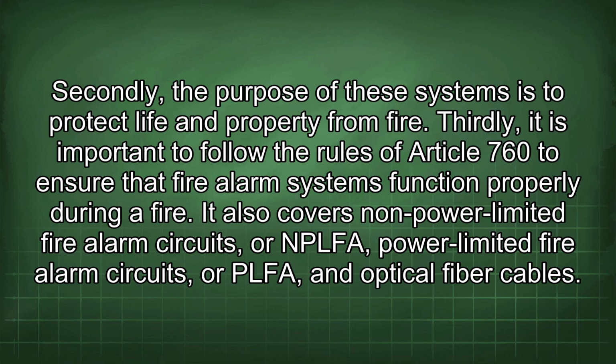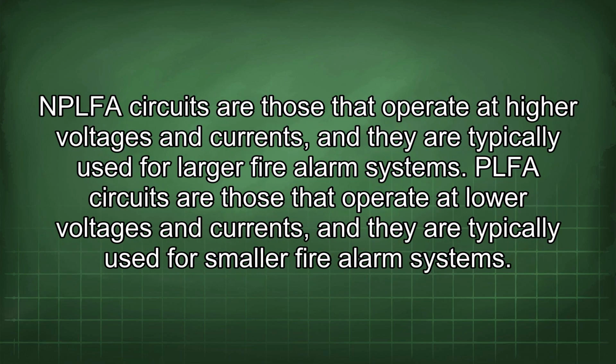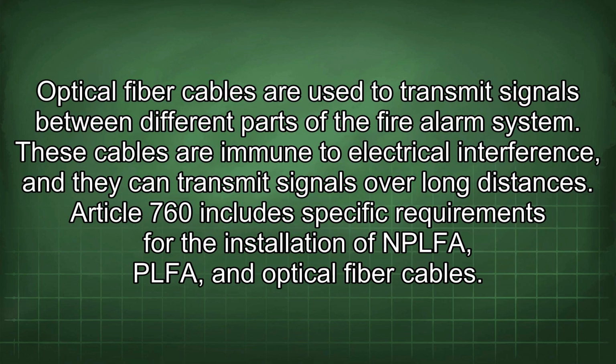NPLFA circuits are those that operate at higher voltages and currents, and they are typically used for larger fire alarm systems. PLFA circuits are those that operate at low voltages and currents, and they are typically used for smaller fire alarm systems. Optical fiber cables are used to transmit signals between different parts of the fire alarm system. These cables are immune to electrical interference, and they can transmit signals over long distances. Article 760 includes specific requirements for the installation of NPLFA, PLFA, and optical fiber cables.